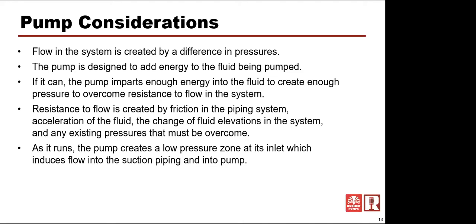This was the pump off, motor off, sitting there with a laser alignment on it. Just as you walked from one side of the pump to the other, the alignment would change. So how in the world would you ever be able to maintain any kind of positive alignment between a motor and a pump shaft if your base isn't proper, if it's not correct? So the installation is extremely important, and there's a lot of things to look for.